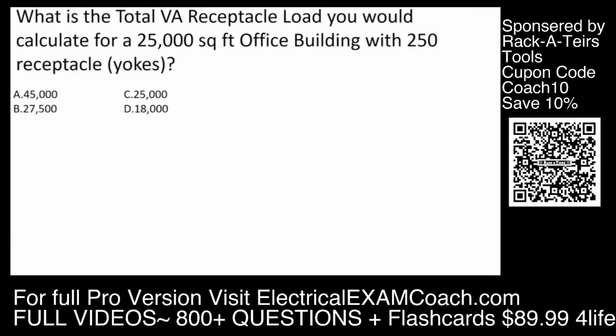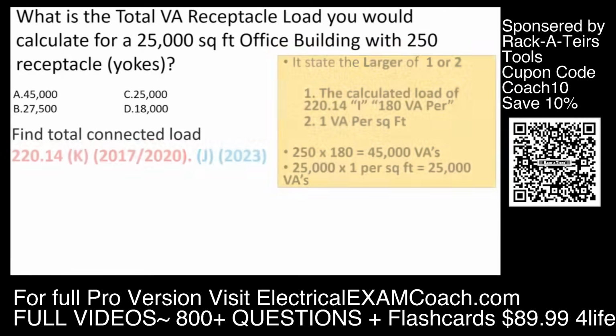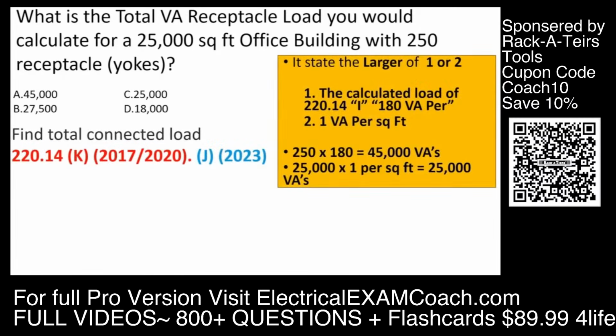What is the total VA receptacle load you would calculate for a 25,000 square foot office building with 250 receptacles? First, we're going to find our total connected load. To do that, we're going to head to 220.14K if we're in the 17 or 20, and we're going to head to 220.14J if we're in the 2023. Same information, different name. Both of them state that we must select the larger of one or two. So we're going to do two different calculations and select the larger of the two.